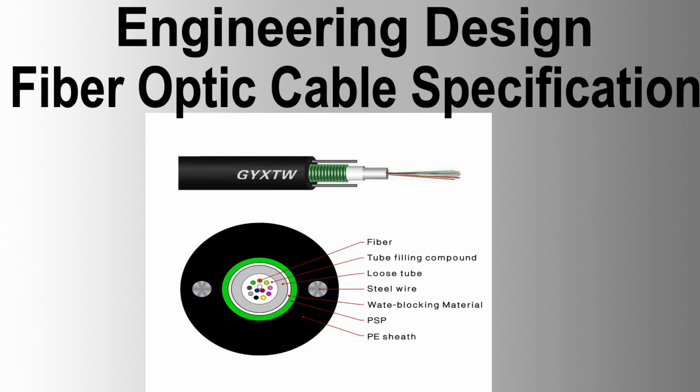Jointing pit installation. A cable jointing pit shall be installed at 4 or 6 kilometer distances along the pipeline, depending on the lengths of the cable on each drum. The cable jointing pits may be the same as the cable access pits used to blow the cable during installation.